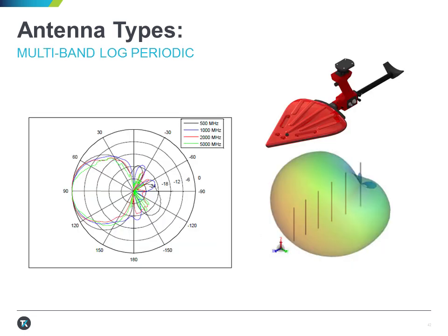Common today in the industry are what we call multi-band log periodic antennas. These antennas cover a very, very broad frequency range from VHF to high UHF. This slide shows us what the antenna radiation and reception pattern is for a common log periodic antenna. You can notice that it is quite directive. However, it's not as directive as, let's say, a Yagi antenna.